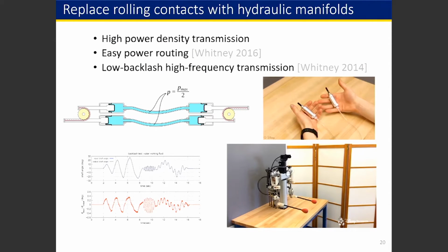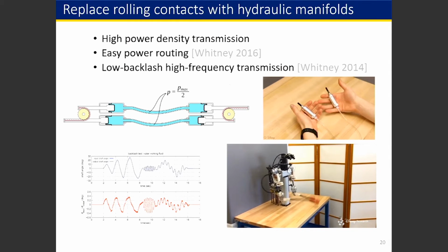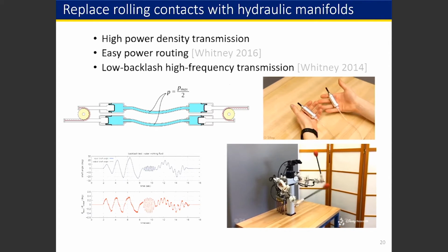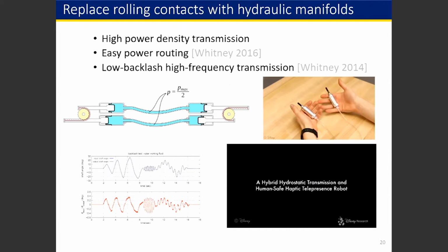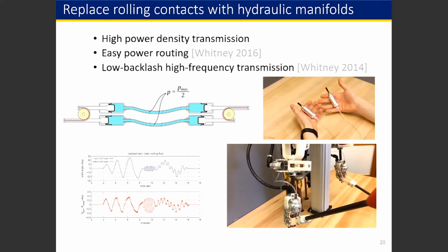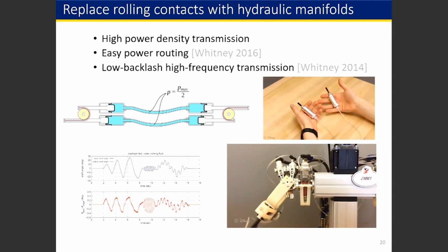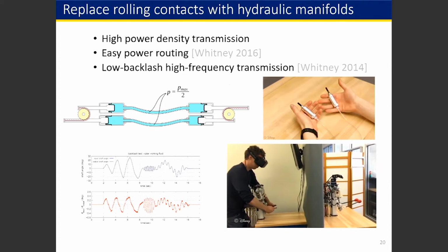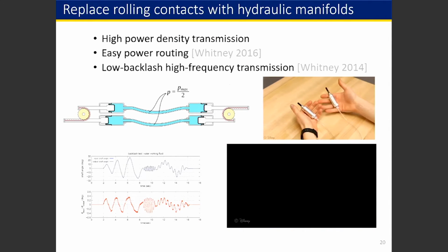We were quite inspired also by some of the, let me play this little video real quickly. I'm sure some of you have seen this in robotics, it was quite a milestone. Here you have a fluid circuit, and you'll see in a moment, someone is teleoperating this robot with a passive hydrostatic transmission, and it achieves a very high bandwidth and a fair amount of constraint force support. Oh, there you see. So it's teleoperated. It's really quite impressive. We were inspired, and they're using rolling diaphragm cylinders and hydraulics, water, not air.